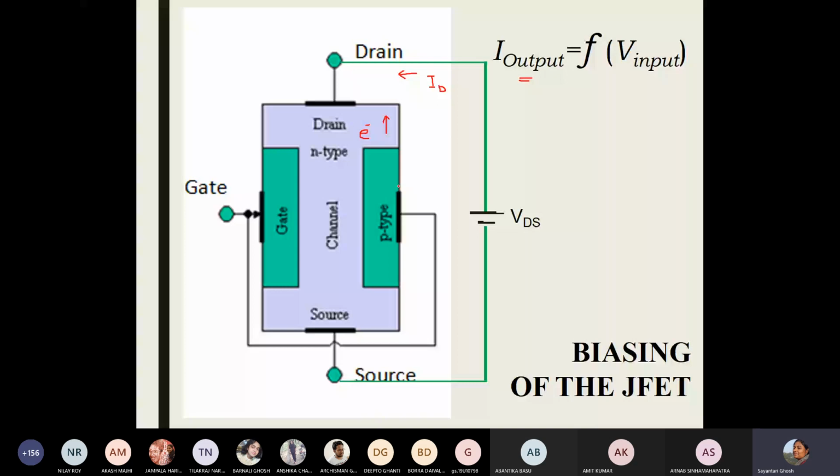So this is what we do. We change the voltage. And the orientation of VDS should not be opposite, because electrons are flowing from source to drain. Electrons should move towards the drain and be repelled from the source, right? Electrons should be attracted towards the drain, so the positive side should be towards the drain, because they should feel a positive attraction towards the drain terminal, right?